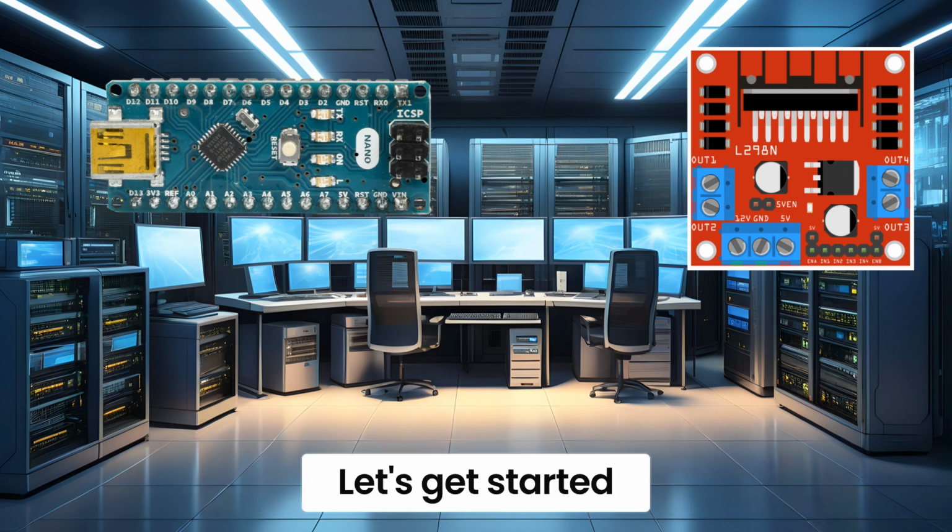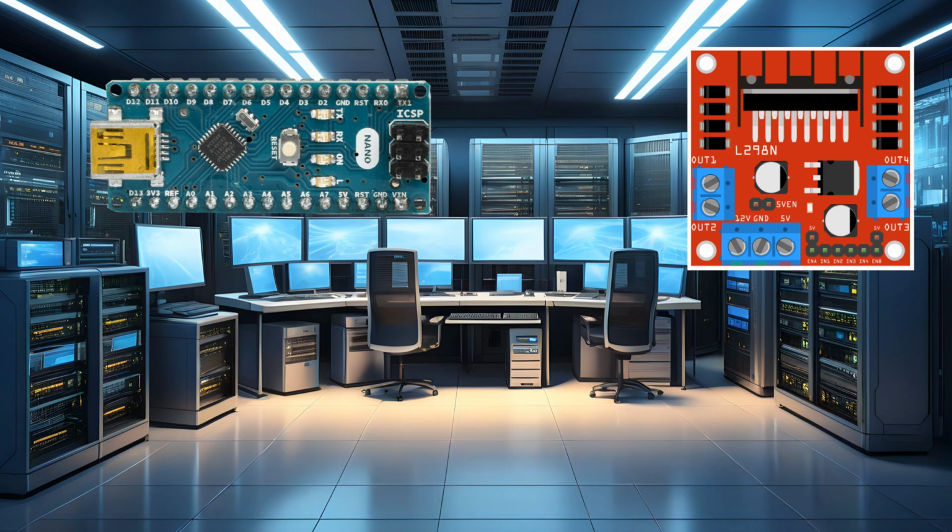Let's get started. So, what is an H-bridge motor driver? It is a circuit configuration that allows a voltage to be applied across a load, such as a motor, in either direction. By controlling the switches in the H-bridge, you can change the direction of the current flow, thus changing the direction of the motor. The L298N module simplifies this by providing an easy-to-use interface for controlling the switches. It has input pins for controlling the motor direction and speed, and output pins for connecting the motors.